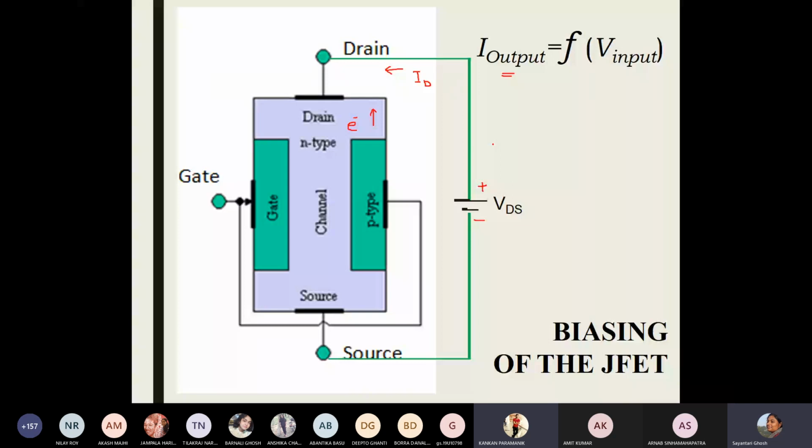Okay. So I guess it is clear that you always place your battery such that the carriers get attracted towards the drain terminal. So see what is the sign? The opposite sign should be connected to drain. So this is kind of the thumb rule of attaching your VDS. Once you attach your VDS, now you know which way the current is flowing. That is the second thing that we know by now.